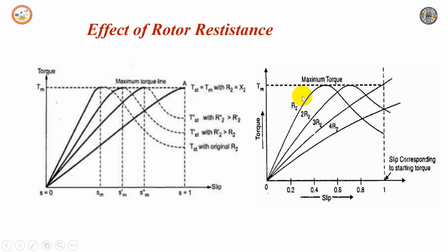If such resistance is kept permanently in the circuit, there will be larger copper losses and hence the efficiency of the motor will be poor. So such added resistance is cut off gradually and finally removed from the rotor circuit in the normal running condition of the motor. This method is used in practice to achieve higher starting torque, and hence resistance in the rotor is added only at the start for good performance at start, and in the running condition it is ensured that the resistance is removed.